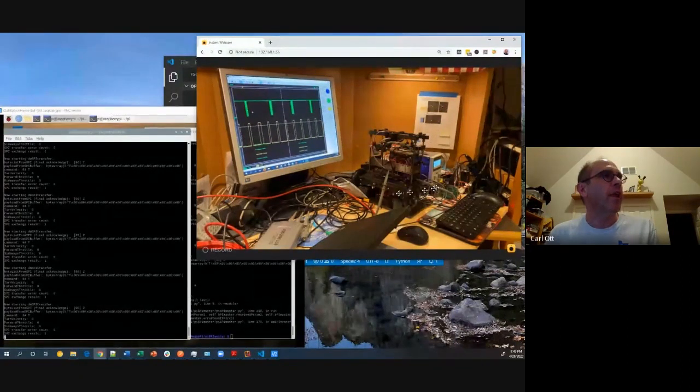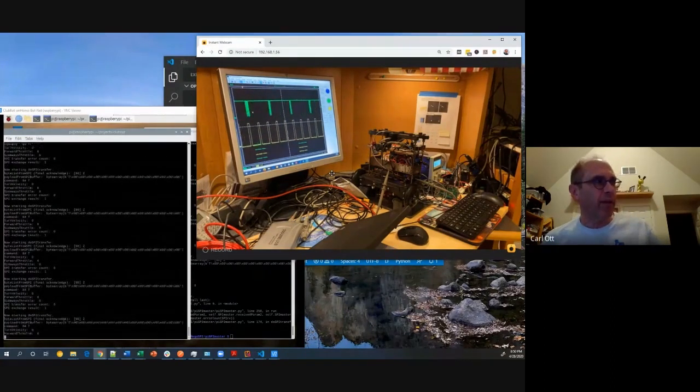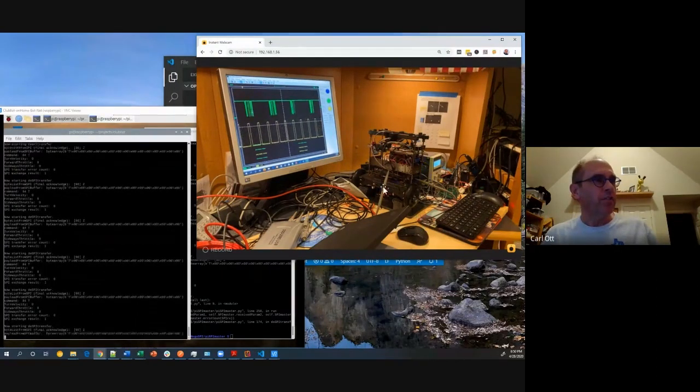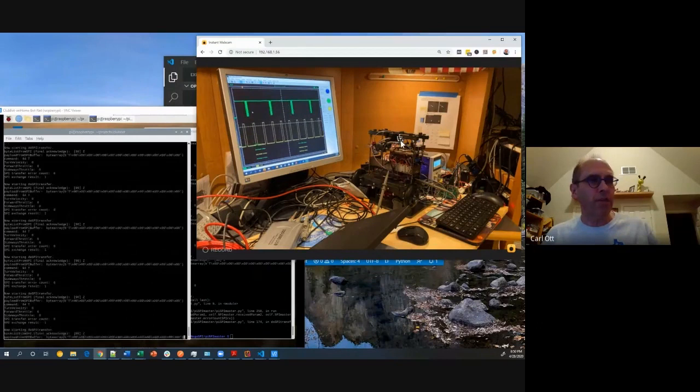Then there's another problem. I have a just-stop-everything safety feature built into the Arduino. If the wheels are turning relatively fast when I hit that, it actually resets the Arduino and the Raspberry Pi. I don't like that. At one point it actually corrupted my GitHub repo. So I've got to solve the EMC or voltage power supply problem, whatever's going on there. But anyhow, we're getting close to this actually being a mashup where it's a differential drive Club Robot being driven by the donkey car top.